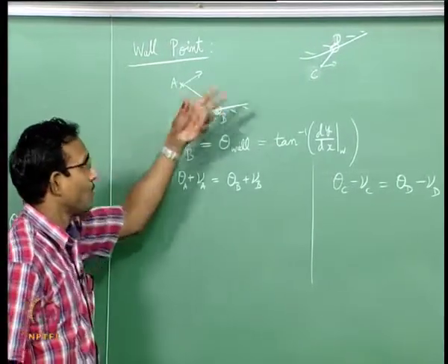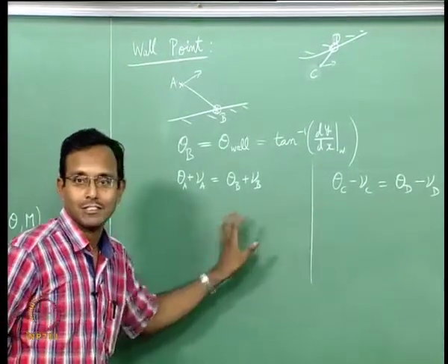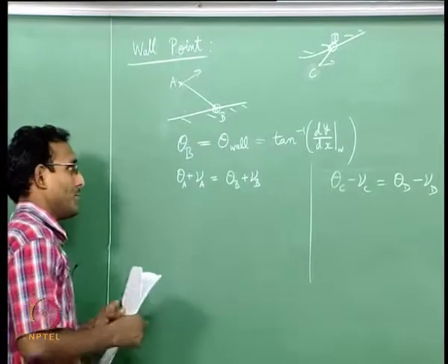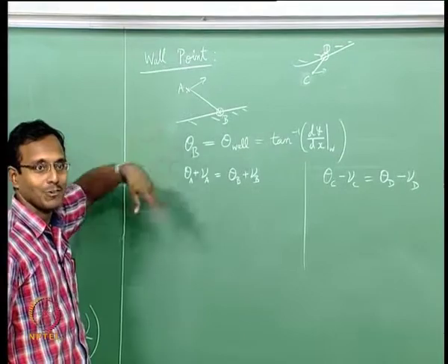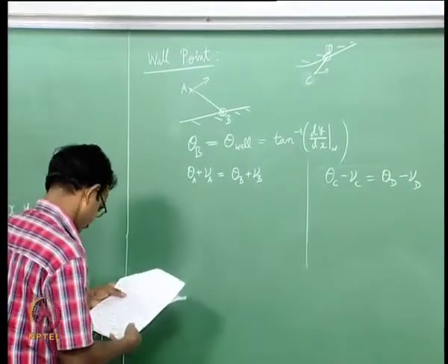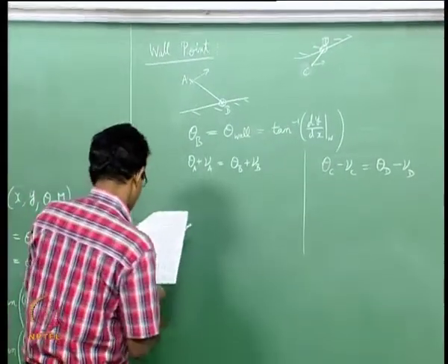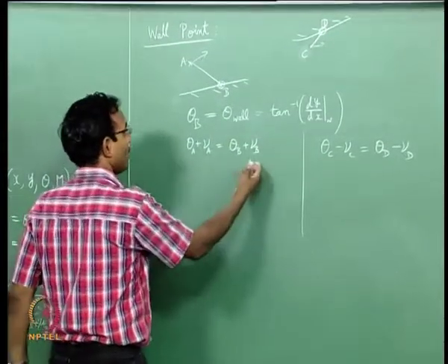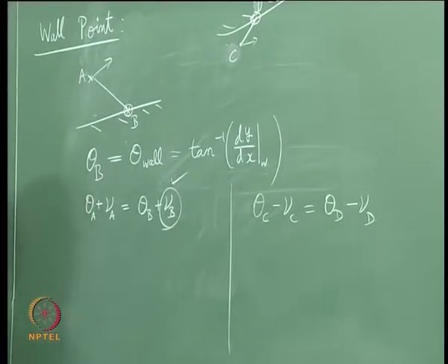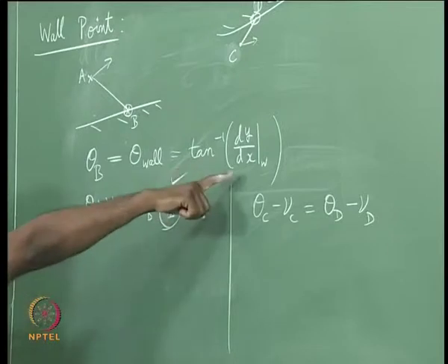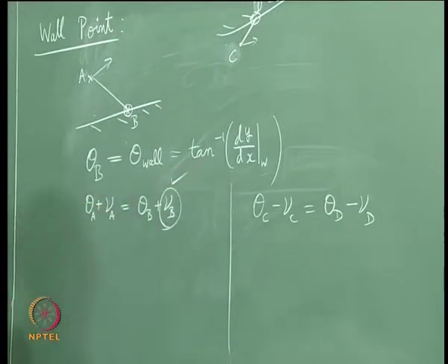Depending on what hits the wall, your subroutine should adjust that slightly. So, your subroutine can have two parts, or you can write two separate subroutines, wall for negative characteristic, wall for positive characteristic, something like that. Now, what is the unknown here? Only unknown is this. So, I can find it directly, everything else is given, assuming you already know the location on the wall. It is not really known. Now, we will go back and look at how to find this point.